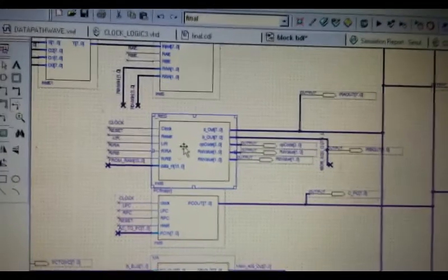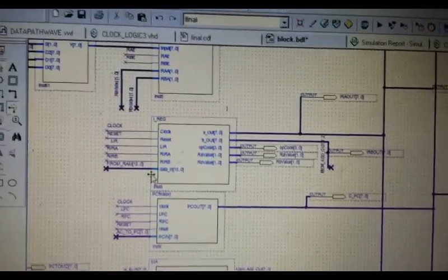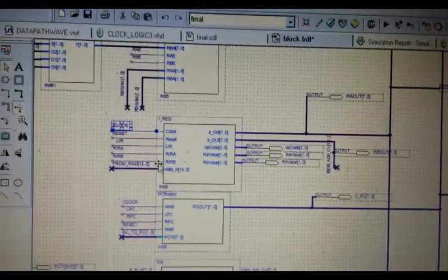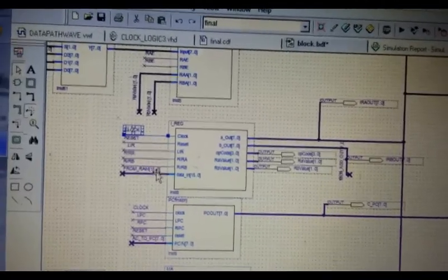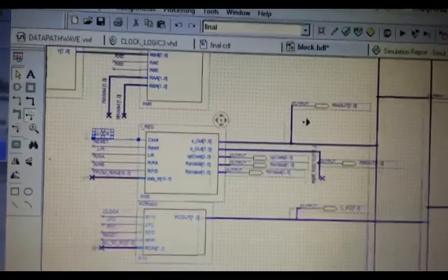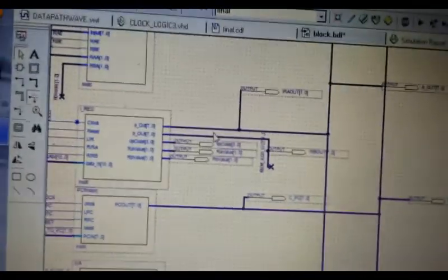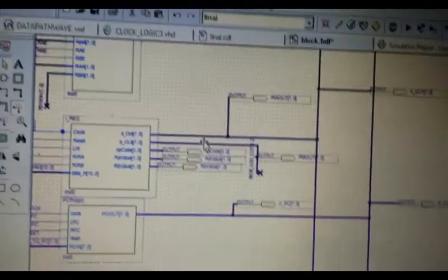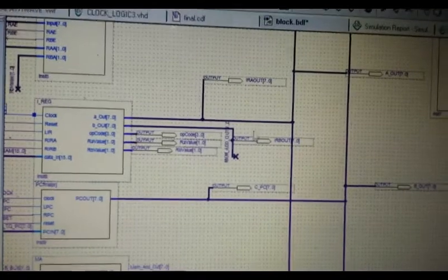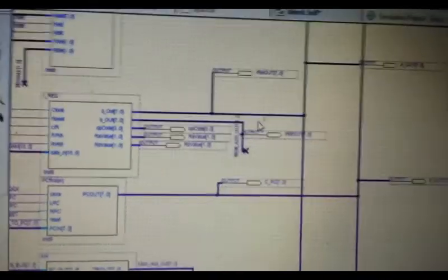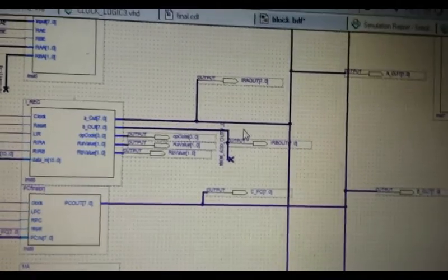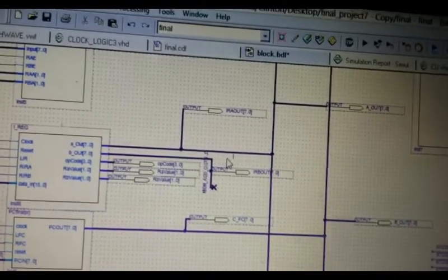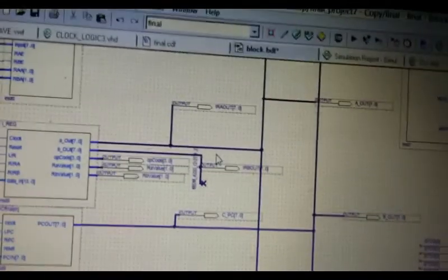So the inputs to the instruction register are the clock, reset, load instruction register, read from the A port, read from the B port, which is right here, and the data that comes in is straight from the RAM. The outputs are actually identical. They both contain the 8 least significant bits. With our design, what the assignment called for was to have the memory address or the constants just in the 8 least significant bits. So the difference between the two ports is just the output connections.